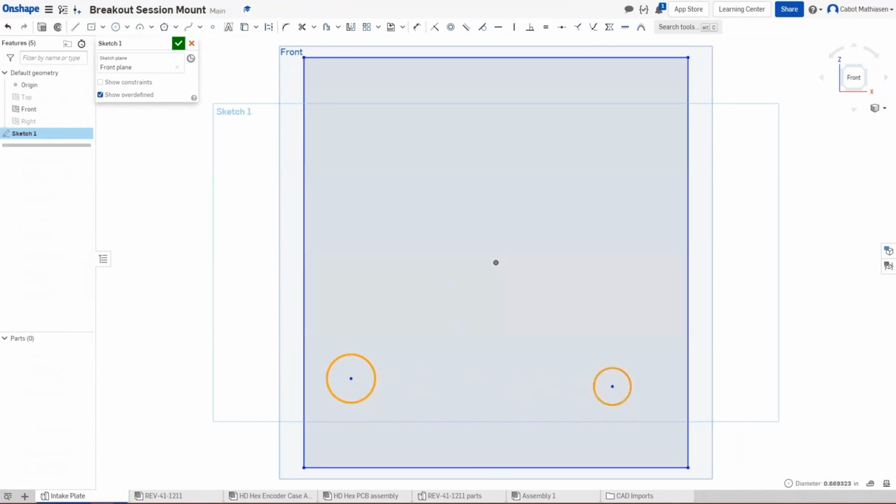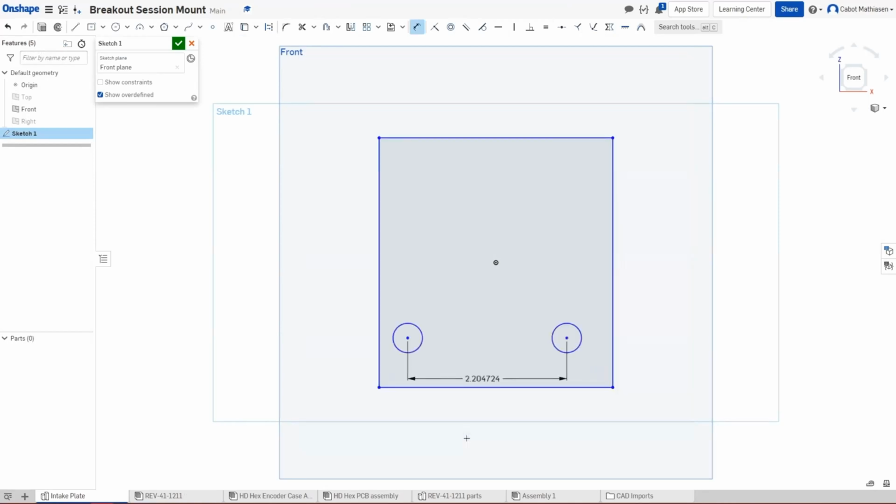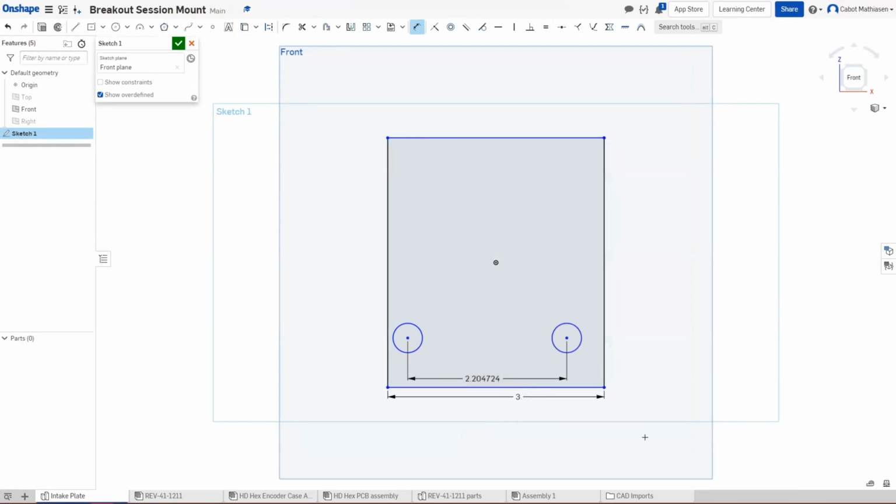So I just placed those down, and I made this horizontal by clicking on the center points of those and pressing H. I now just copy and pasted the number from beforehand and put that for the spacing between those circles so that they are the same length apart, so that they will match up and they can be constrained together. I then dimension this to 3.